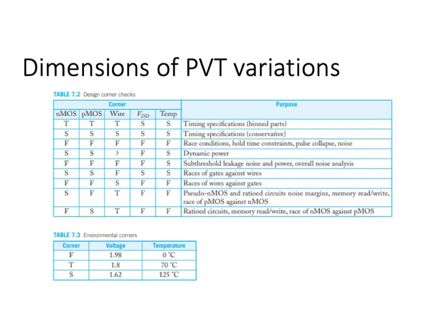So typically, to understand this range of variations, simulations during the verification step are run in what we call process, voltage and temperature, or PVT corners. So you would not only simulate the performance of your circuit under expected operating conditions, that is the typical corner. So this is, let's say, for a 1.8 volt process, typically assumed to be operating at about 70 degrees Celsius, and typical NMOS and PMOS width and length.